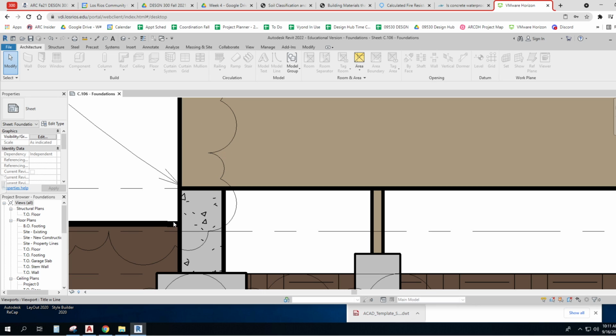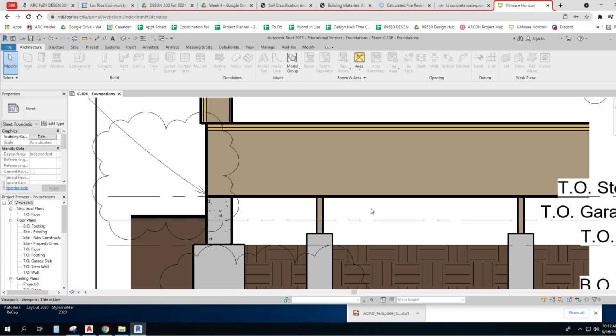That's because termites generally can travel 4 inches in the air and then they dry out and die and come down. So we want at least 6 inches of air before you get to the wood for them to travel over. Although if it's slab on grade, we want at least a 4-inch slab so they can't just crawl up the outside of the slab and get in.